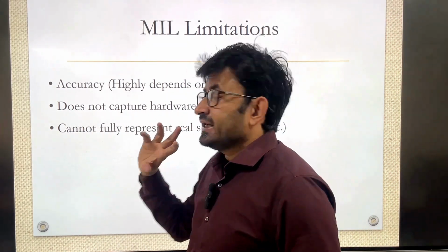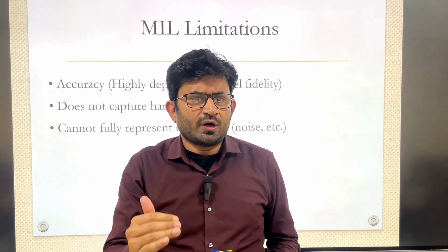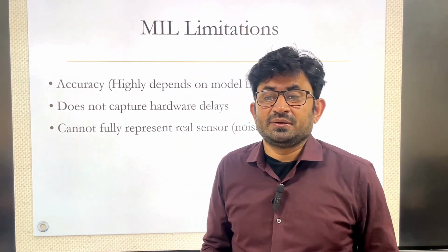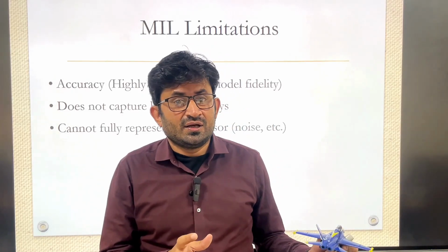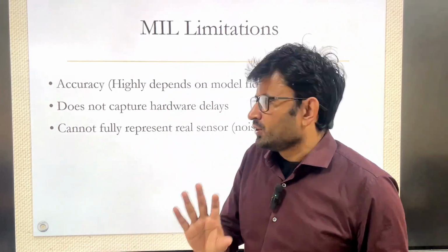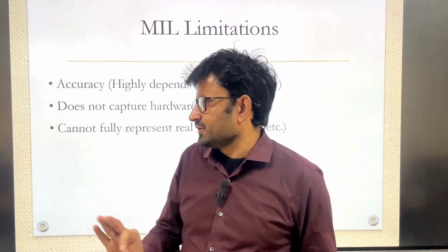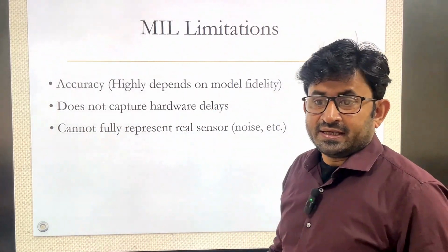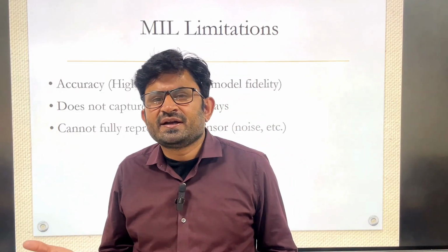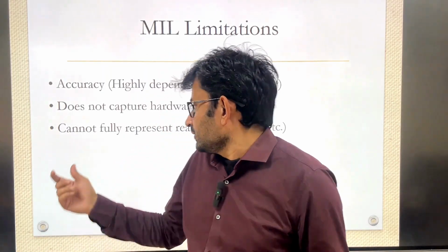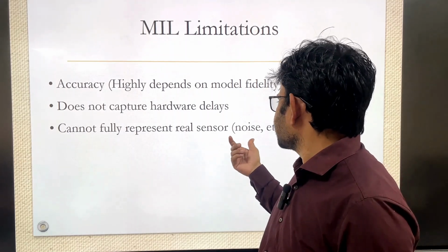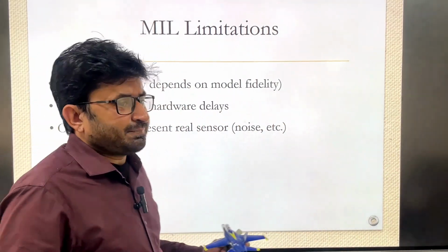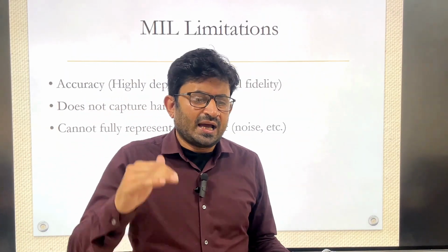It does not capture the real hardware delays. Although, using Pade approximation, as I explained, you can model the delay and actuator dynamics. You can put the physical limit constraint on the actuator in Simulink. But whatever you do, you will have some kind of problem, inaccuracy. Okay, so it does not capture the real hardware delays. And of course, in reality, the sensor will behave in a very different fashion. Okay, so it cannot fully represent the real sensor noise, etc. But whatever is possible, try to model in Simulink as accurately as possible.